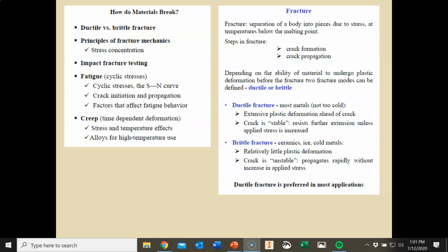A brittle fracture is the breakage or cracking of a material into discernible parts, from which no deformation can be identified, basically a clean break. It is characterized by rapid crack propagation with low energy release and without significant plastic deformation. The fracture may have a bright granular appearance. The fractures are generally of the flat type, and chevron patterns may be present.